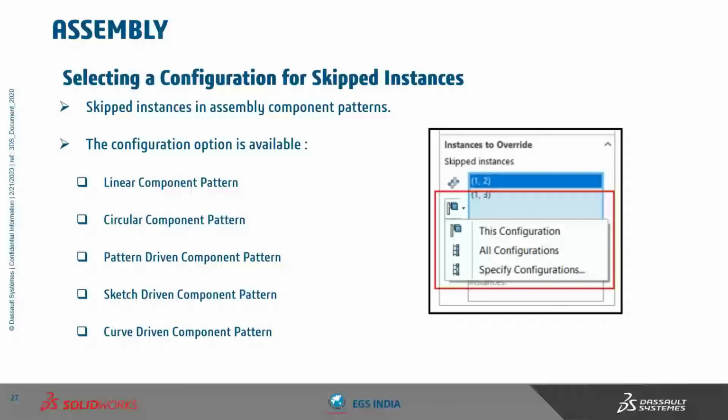Selecting a configuration from skipped instance. Now SolidWorks assembly component pattern skip instances can be configured. These patterns are available in linear component pattern, pattern driven component, sketch driven component pattern, and curve driven component pattern. Now if we need some configuration as skipped instance, we can enable it.